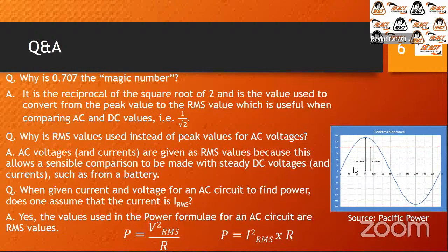All right, so I hope that helps a little bit in conceptualizing this graph. Maybe people thought that when we said 120 volts AC from the plug, the receptacle outlet in your wall, that was peak. No, that is actually RMS. The peak of that voltage actually goes much higher, to 170 volts. That's why the insulation also needs to be able to handle a higher voltage than the voltage that you're saying. You're saying 120 volts, but you see the peak here is 170 volts.